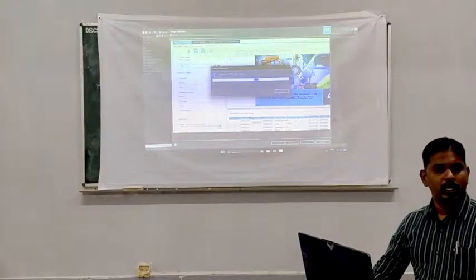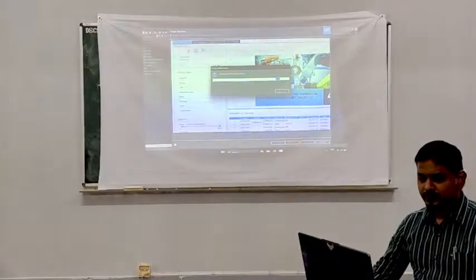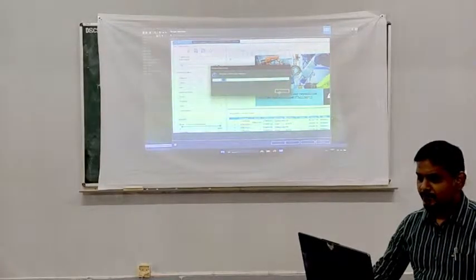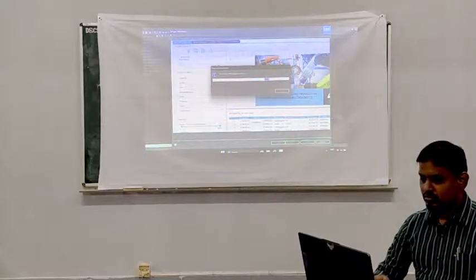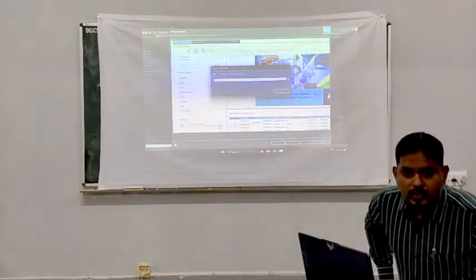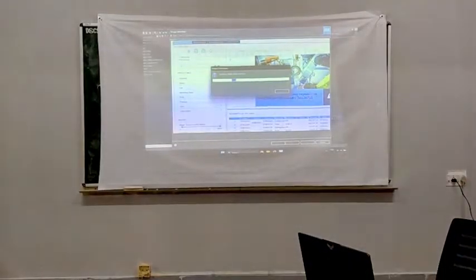Sir, ask Manju to bring one cable. Now you connect it. If you type, no? Wait. No, you type, sir. Here you type the board name. Not here, here. Nucleo L476RG. That you select. Click it. Now it will show the board. Select and Finish. Select, just click it. Finish. Next.